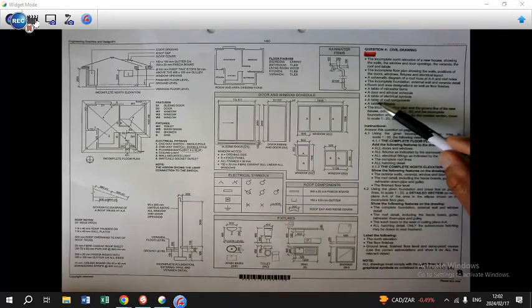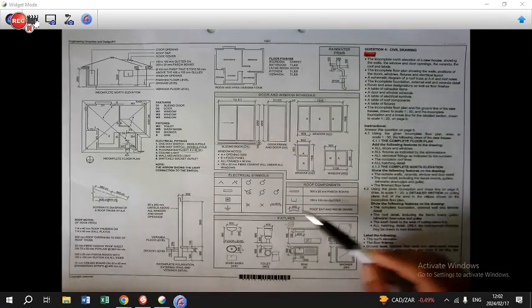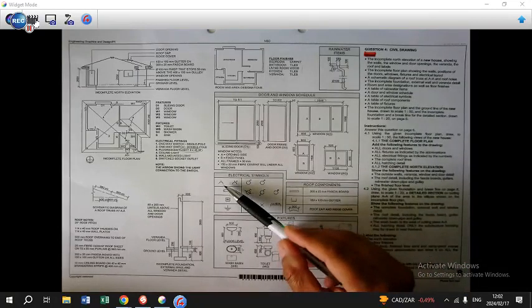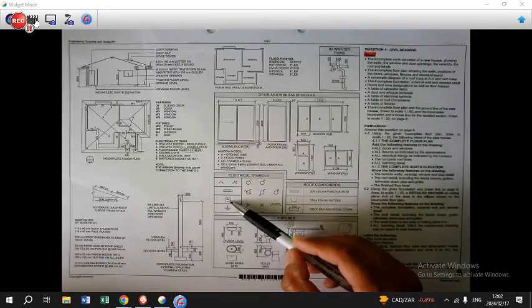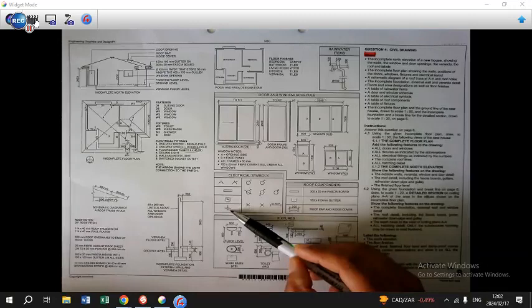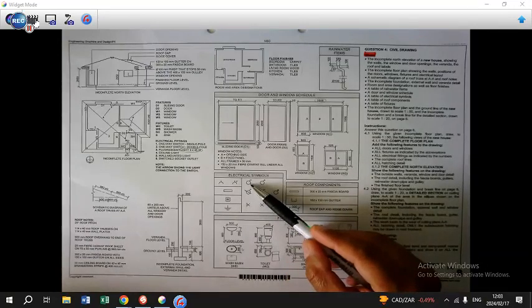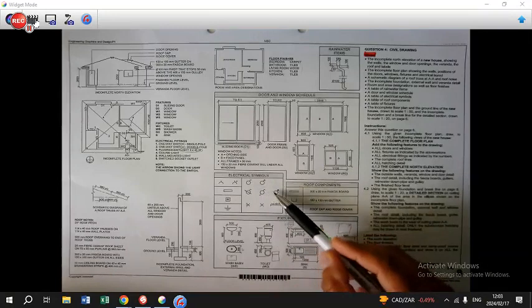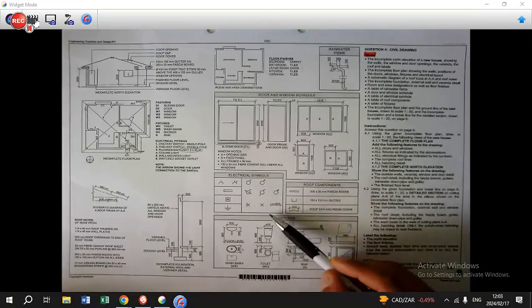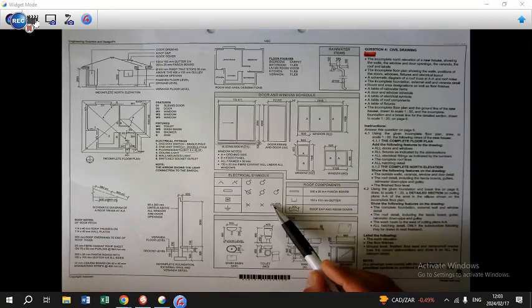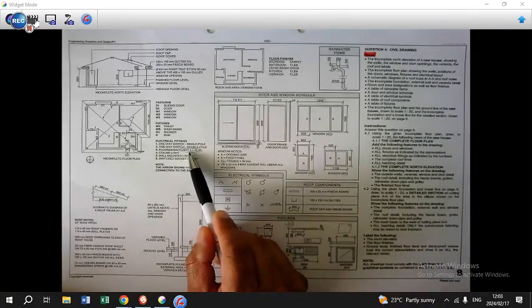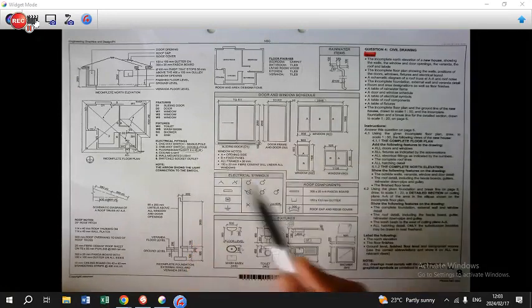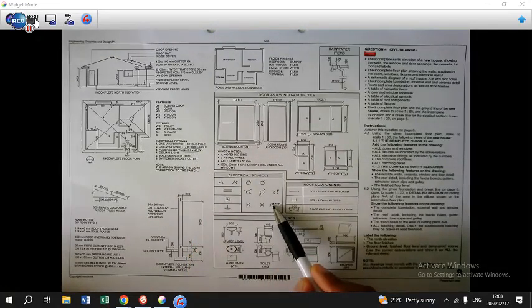Then learners, we have the table of electrical symbols, which you are going to find in this space here, where you have the wall sockets, the distribution board, the watt meter or electrical meter, the earth leakage, the single pole one-way switch, the double pole one-way switch, and all other components related to your electrical symbols. It does state here N times 45 watt, but when we are going to draw it in our floor plan, we will have to include the actual 3 times 45 watt, which is just a placeholder for the 3 which we have there.